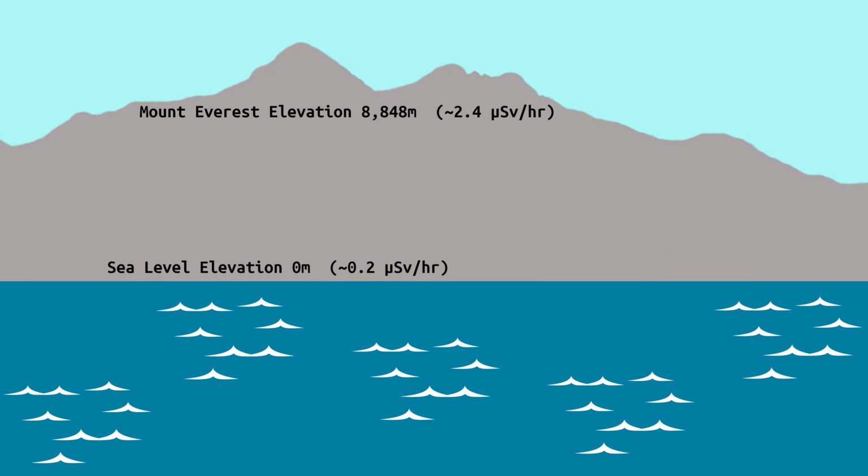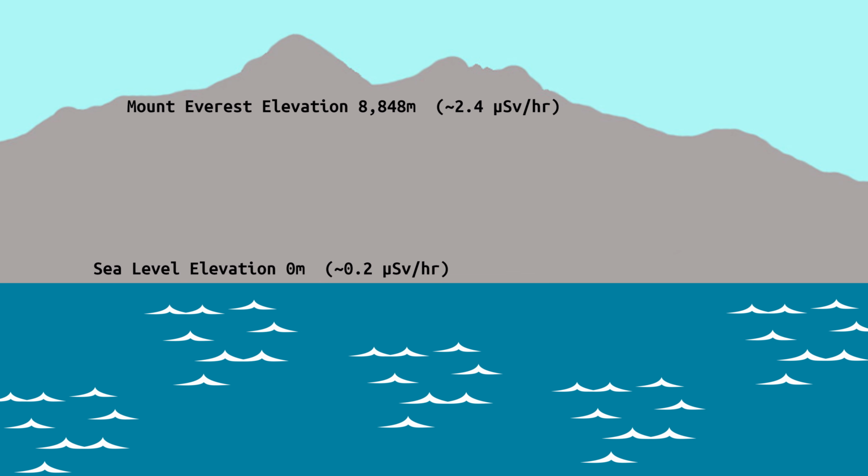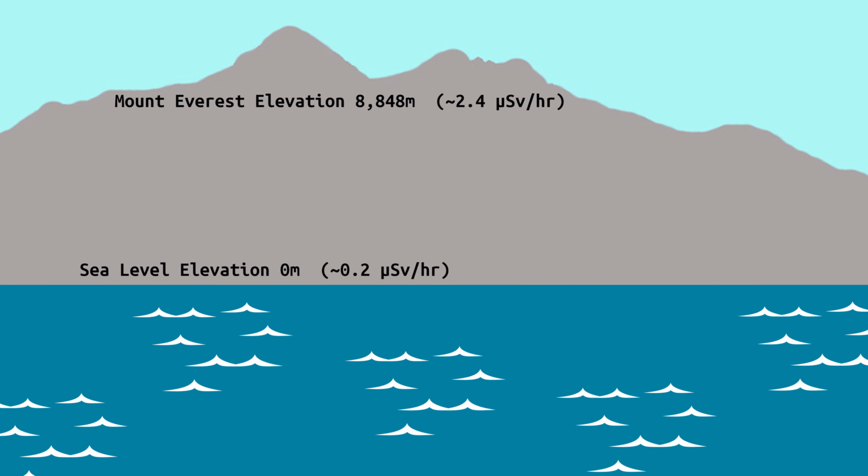Okay, that's enough talk about cosmic rays themselves, but if you really want to be precise in predicting your expected rate of bit flips, you also need to consider what altitude your computer operates at. Obviously, the higher you are, the less of a protective atmosphere you have to protect you from radioactive particles from space. Some reports suggest that a Mount Everest climber would receive an expected radiation dose that's 5 times as much as someone who stayed at sea level. Since higher altitudes also have rarefied atmospheres, cooling systems that rely on air will become less effective. This could lead to unexpected overheating, which also causes bit flips.